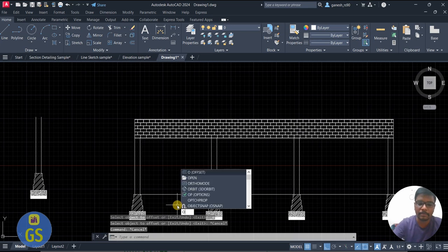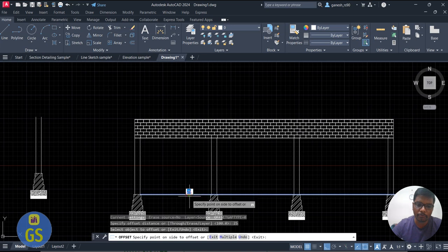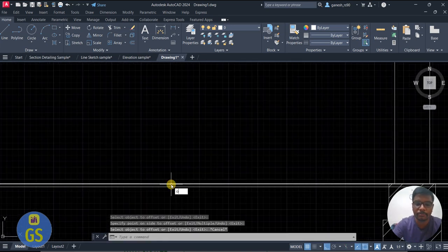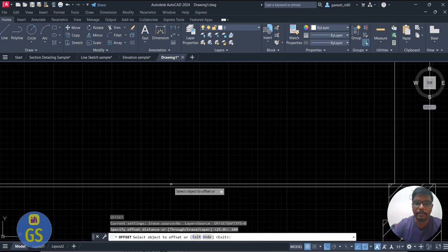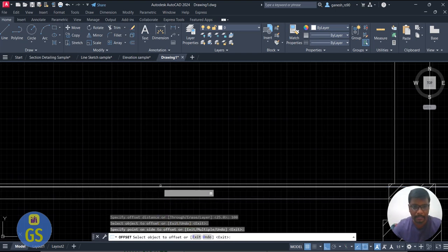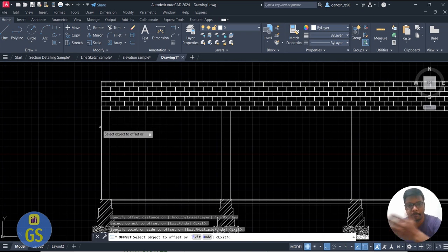So as per the detailing, if you want 25 mm first, then you can show the first 25 mm, and then for the next offset you need 100, so the second line is 100. So what is that? That is nothing but, as I showed, the floor finishing and then the slab thickness. So 100 mm slab thickness. Over here we can also show it at the top level. Presently I have not shown it because I have shown brick walls.